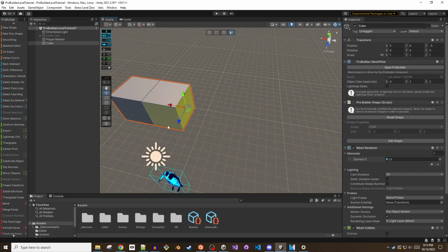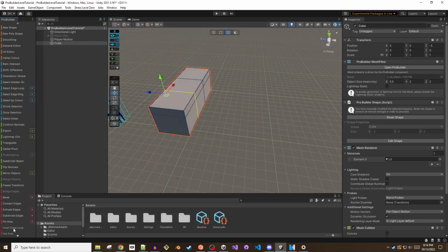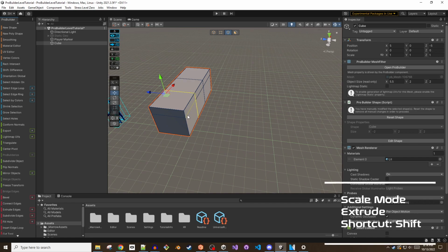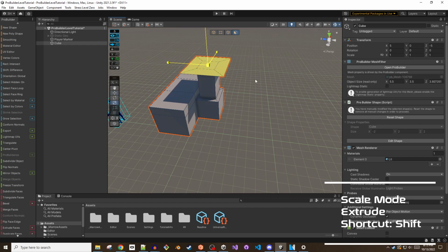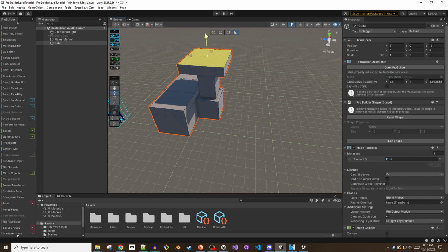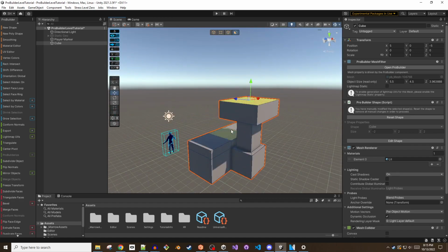The face, vertex, and edge drag takes existing geometry and manipulates a face, edge, or vertex in a direction to change the object's shape. There is no dedicated inset tool in ProBuilder. Instead, holding Shift to enter extrusion mode, and then scaling down will perform an inset. This is commonly used to create a window or vent entrance in a wall. Extruding and scaling outward will grow the selected face radially. Using this operation on a cylinder and scaling the face up or down is a quick way to add detail.